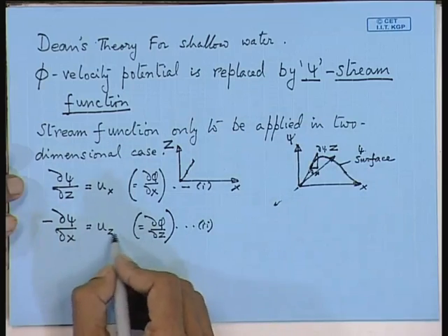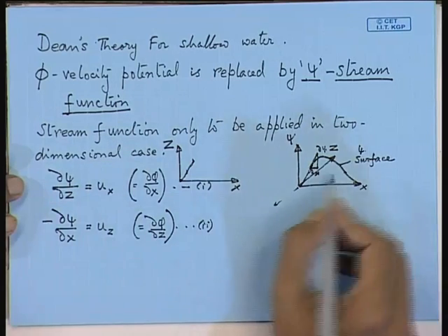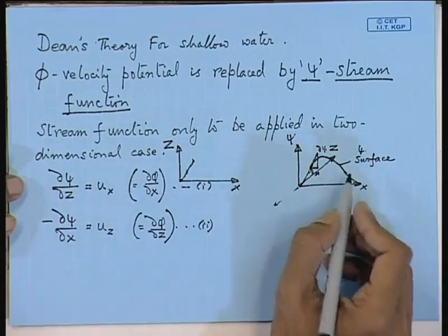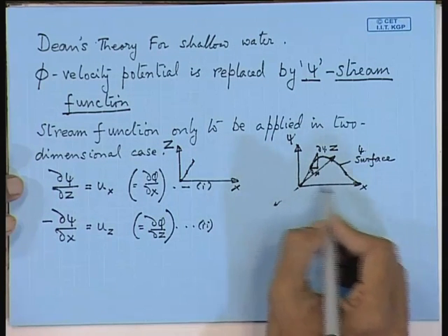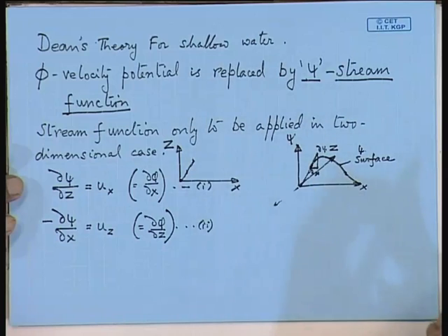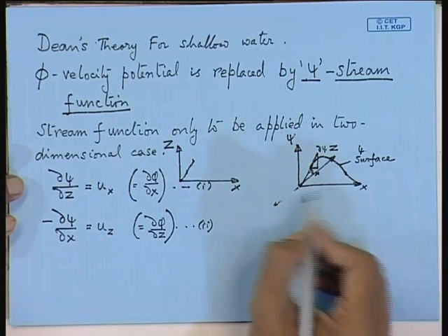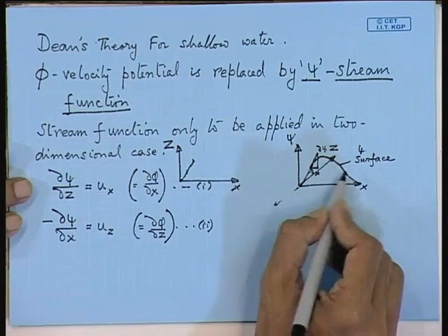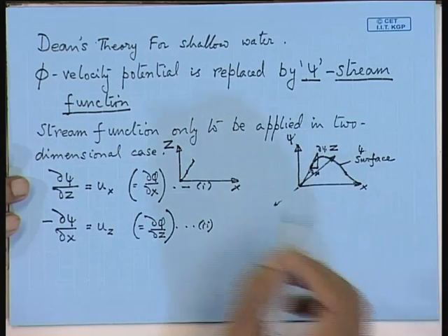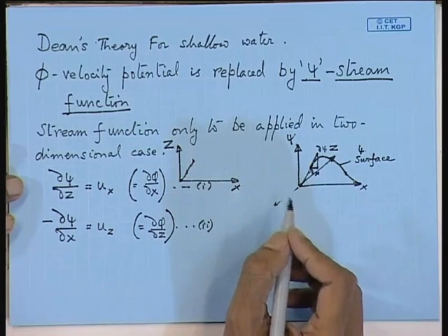So, this actually gives us both the magnitude and also the direction. So, actually you have to plot a psi surface with respect to x and z. Now, you do the other term, that is del psi over del z, but that will give you velocity in the x direction. So, this is the gist of the psi function.